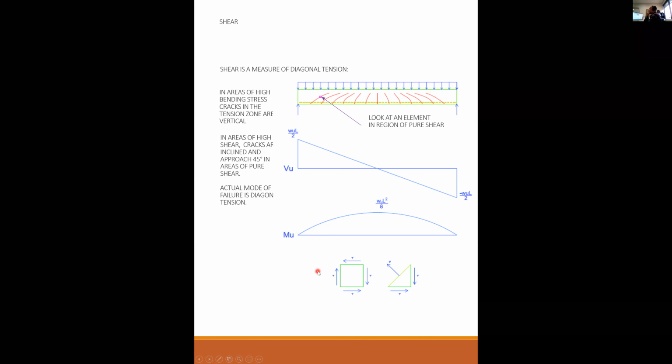And you remember from your mechanics of materials, from the section that you did on stress and strain transformation, right? You remember all that? With stress transformation, you have a shear stress, you have a sigma X, and you have a sigma Y. And then you could rotate this element at any angle and calculate the transformed shear stress and sigma X prime and sigma Y prime stresses, okay? So that's what we're looking at here. But at the neutral axis towards the end of the beam, there's no sigma forces on this element. You don't have any significant axial stress on this, you just have shear stress.